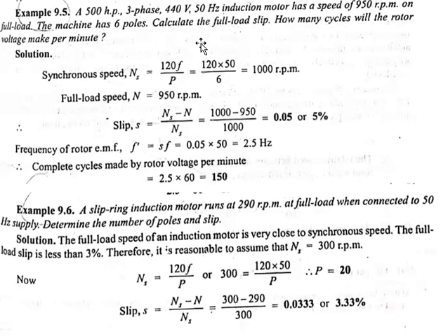So here a few additional things are there which you may not need. So don't worry if additional information is given. 440 is given, which is not required. 500 HP is not required. Frequency is required. F is equal to 50 Hz. N is 950 RPM. And it is running on full load. Don't worry about what load it is. They have mentioned it is running on the full load. We have to calculate full load slip. Just read it as calculate the slip. That is sufficient. And the machine has P is equal to 6.